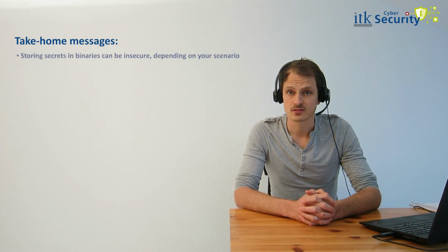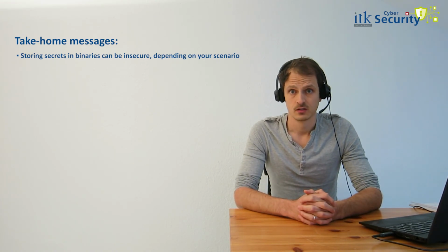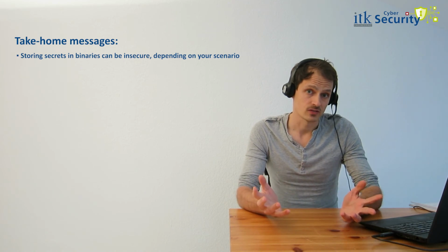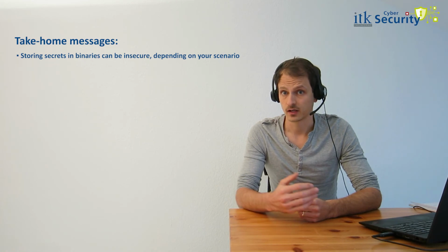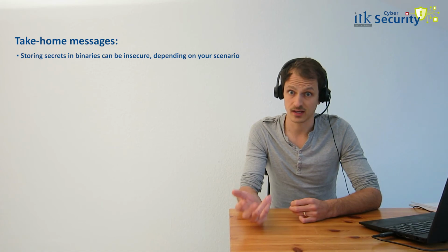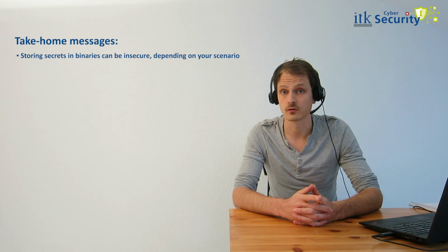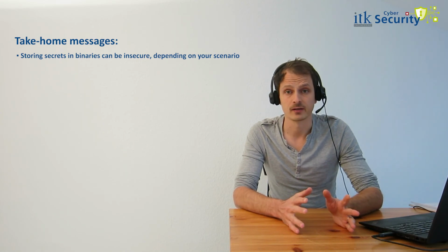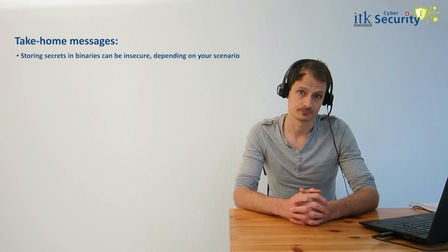So take-home messages. What did we learn in this video? Well, for one, we learned that storing secrets in binaries is not as secure as you would think. Whether this is okay for your device or not actually depends on your scenario, on your attacker model. Are you assuming that the attacker is not able to get his hands on the firmware in any way, be it by physical extraction or via software vulnerability to read it out remotely? Then you're probably fine. However, if you're not sure about this, then you probably have to do something.